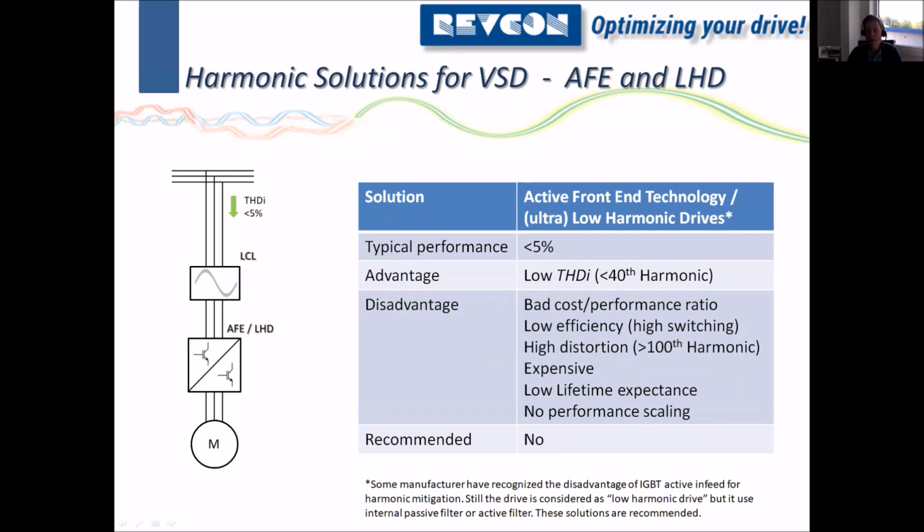You will have a reactive part in this area, but in the overall performance, it's quite okay. The main problem that I see with this topology is that if you don't have any regenerative power, this technology is a little bit of a waste of energy, because you have the high switching device at the input. So it's not only about the installation cost of this solution, which should typically be quite much more than a passive solution. It's also about the technology and that you have the high switching device.